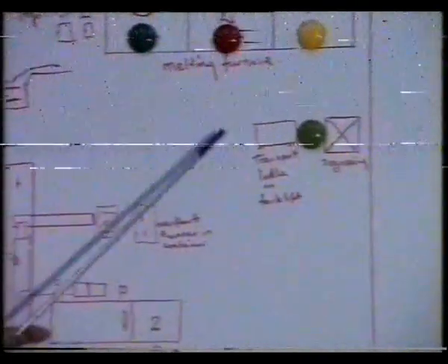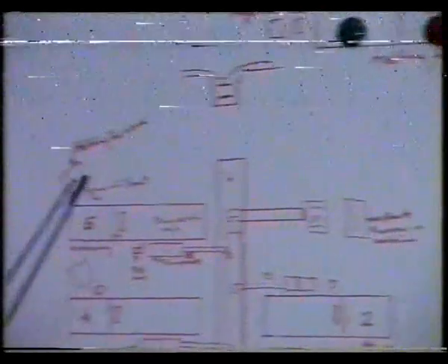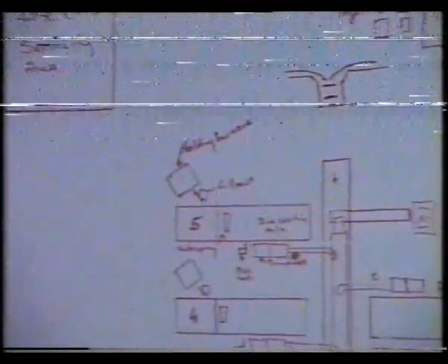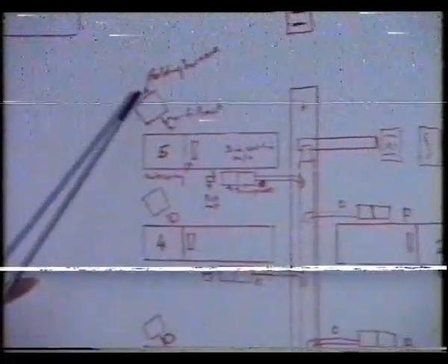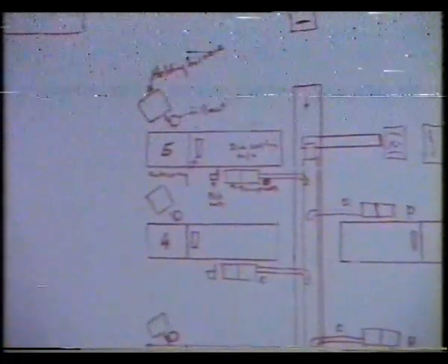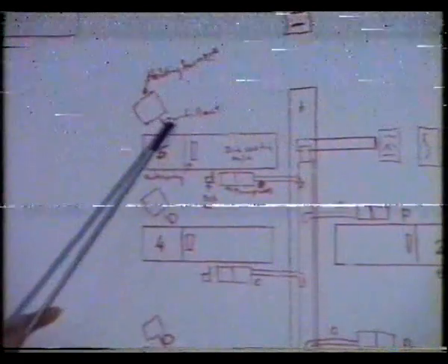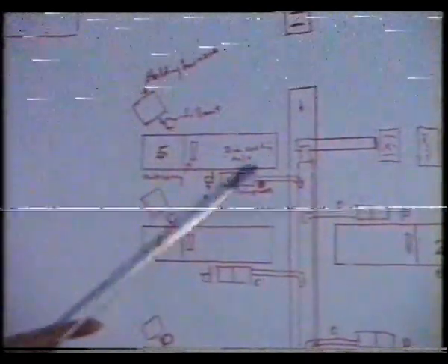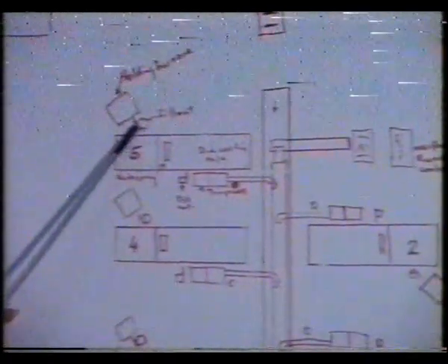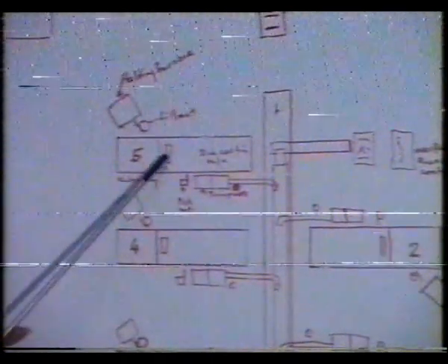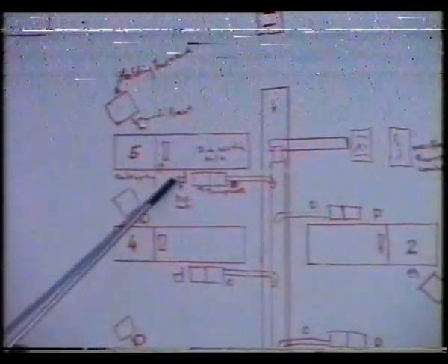After this, the forklift will bring the metal to either of the 5 machines and pour into the holding furnace. From there, we have a die casting machine with fume mat, auto spray, pick mat, and trim press.